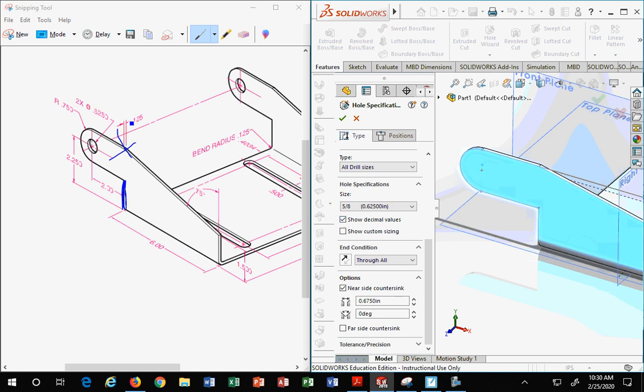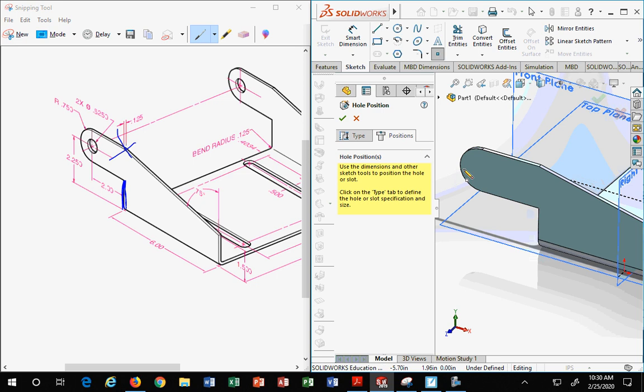That's a 6. Yeah, we had that conversation already. That's a 6. I know. It kind of looks like a chopped off, but that's a 6. Always remember, SolidWorks doesn't tell you what the next step is. You have to know. Pick on position. Remember, if you want to find the center of a circle, go to its edge first, then find the center. Don't try to hunt for it. Keep it simple.